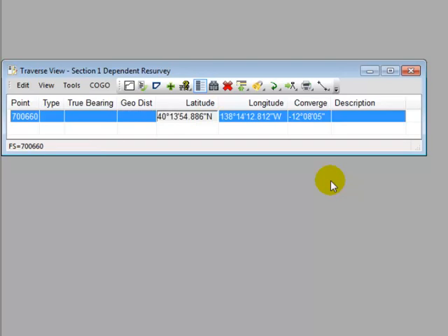Let's go ahead and enter our latitude, which is 43.2100110. So I just enter one decimal place after the degrees. It's positive, so it's north. When I enter a longitude, I can either do a minus or a W. I'm going to do a minus 120.2410266. Traverse PC goes ahead and puts the W in there for me and displays my convergence, which I'm going to check as 3 minutes 59 seconds, so I'm good.